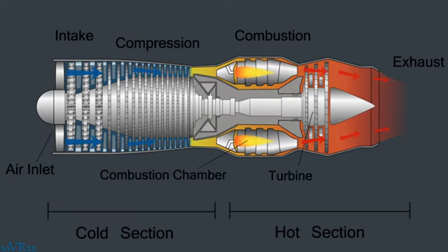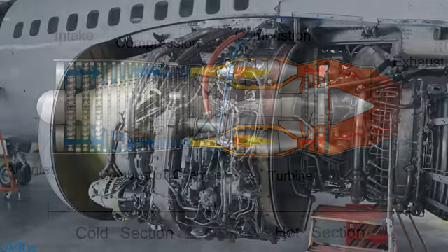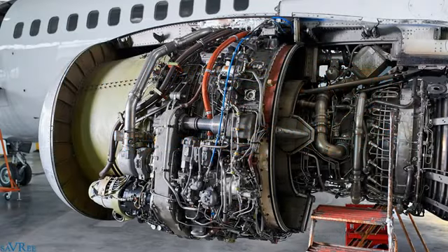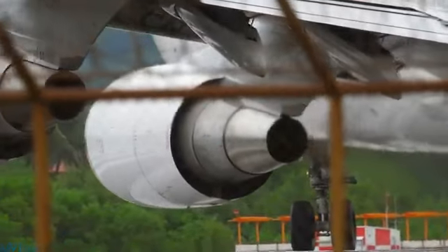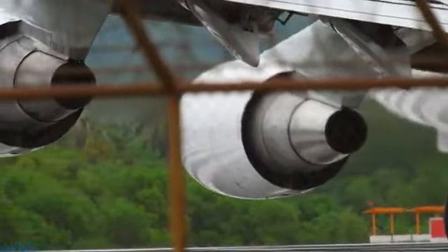Our turbine blades move, our main shaft rotates, and the process then continues. What's interesting about gas turbines is you can use them for many different types of applications. Aircraft engines are essentially gas turbines. They have a very high power to weight ratio, and that's what makes them ideal for usage in the airline industry, where weight has to be reduced as much as possible in order that the aircraft can take off.